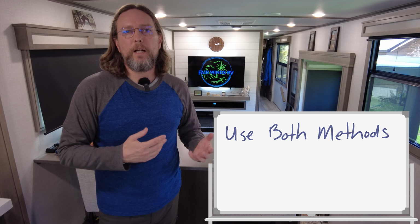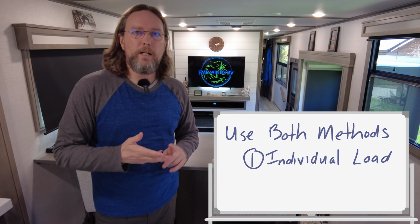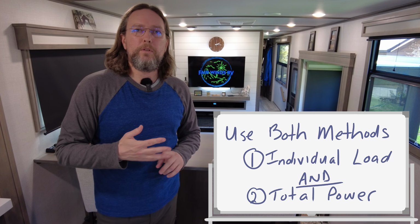One final note on the power audit itself is that I actually recommend using a combination of both methods. So the individual load method and that total power method. And I would do that for two reasons. So number one, when you use that individual load method, it gives you a good idea of how much power each individual item draws in your RV. So if you decide later that you do or don't want to use any of those loads, then you have a good idea of how much more power you're going to use or how much power you're going to save.